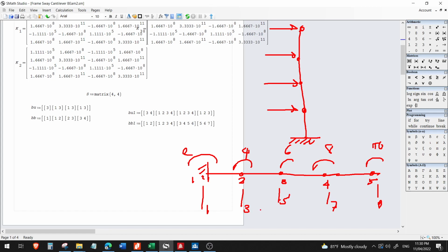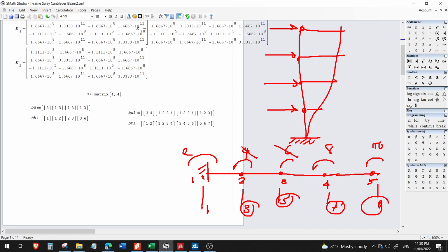But, what will only be activated as displacement are these degrees of freedom. Only those, right? Because we assume an actually rigid slab. So, only translation, such that this is the sway without rotation. Translation only. Okay? So, these degrees of freedom will disappear. So, therefore, 3, 5, 7, 9. So, therefore, our S matrix is 4 by 4. Okay? Because we have 4 unknowns, 4 lateral displacements.